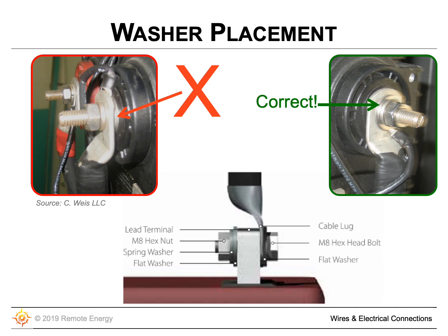And when that cable is cooling and then getting heated up with the amount of current going in or not going in, there can be a lot of contraction and expansion between that copper plated lug and the stainless bolt that's attached to the inverter. So that lock washer can help quite a bit, helping to make sure that that connection stays solid for a really long time.